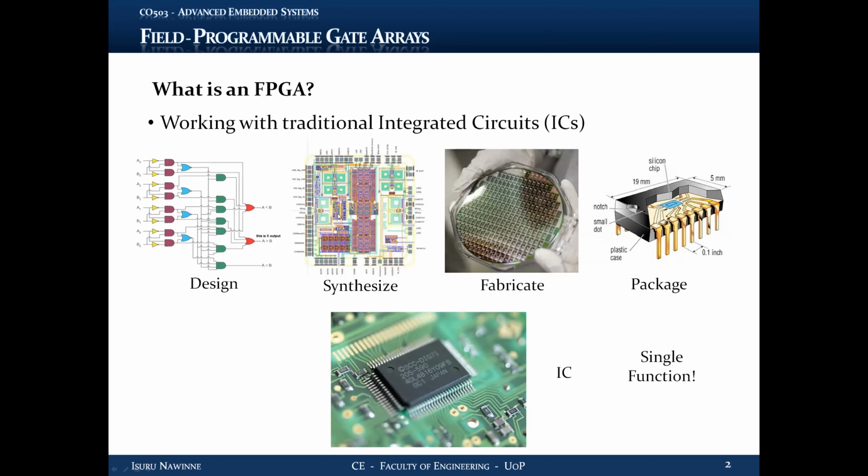In this synthesis step, what happens is you are converting your register transfer level design or the gate level design into, in most cases, a transistor level design. In usual cases, in an integrated circuit design, what you end up with at the end of the day is a silicon chip with transistors etched on it, using the typical process called lithography to dope the semiconductor with certain properties.